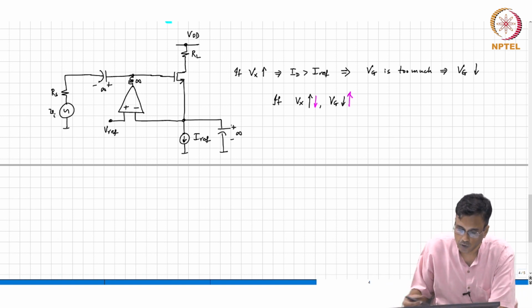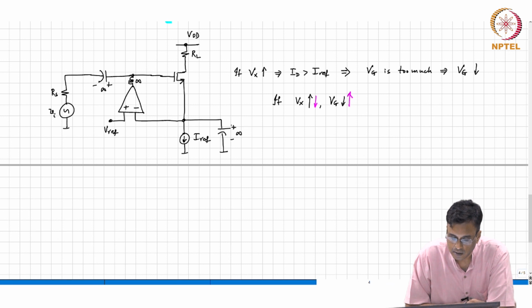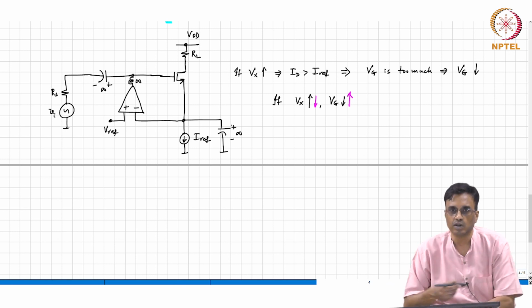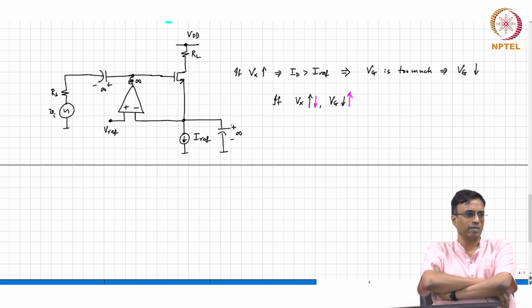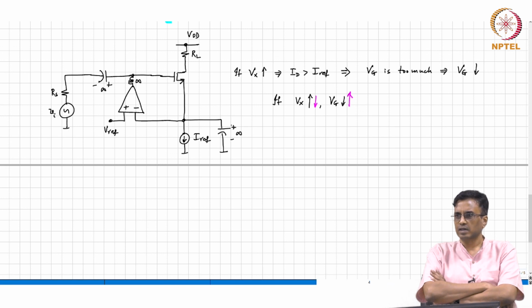So this basically covers all the 4 fundamental ways of stabilizing the bias current of the transistor, right. Once you stabilize the bias current, the transistor is ready for action, and therefore we can realize the properties of the transistor, namely the GM will be very well governed by the bias current in the transistor, which will not vary now even if the threshold voltage changes or the supply voltage changes.